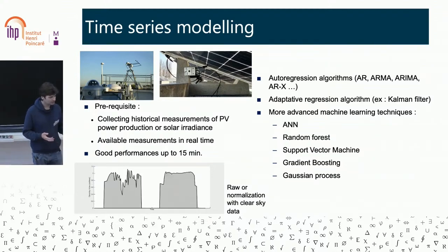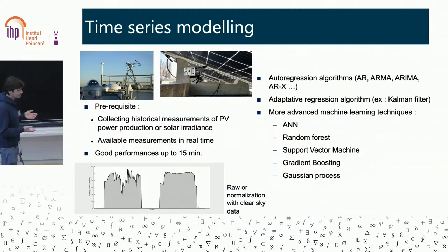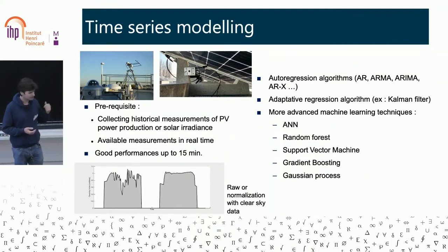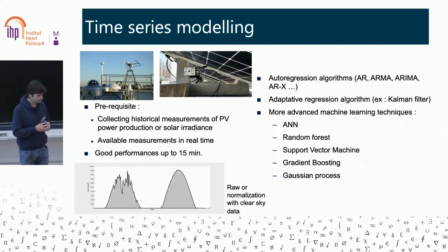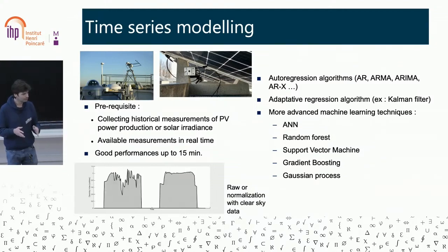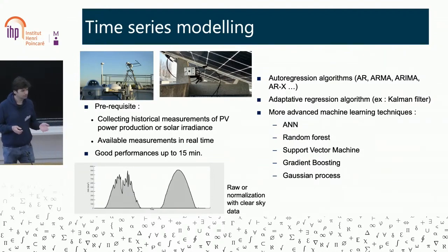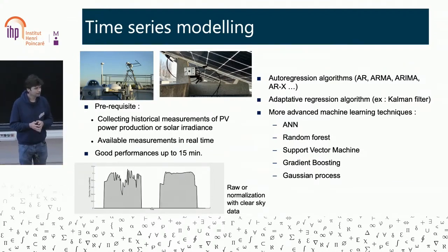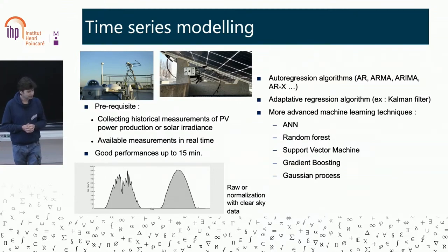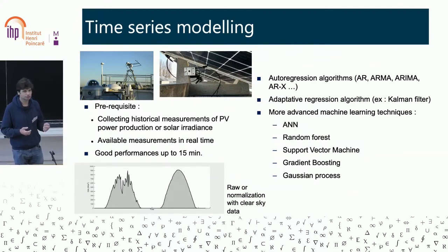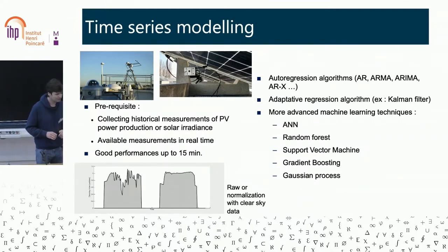You need to collect time series of measurement. Measurement can be, this is a pyranometer, you have it on the left. Pyranometer from CIRTA at Polytechnique. You can collect historical measurements of irradiance or PV power. You can have measurement of PV power if you put an instrument below your PV panel, for example. And it's better if you can have your measurement in real time. It's not the case for everyone. Many industrials, when we ask them, do you have a real-time measurement, they say, no, why, is it useful? No, I didn't know. Okay, so it's not available everywhere.